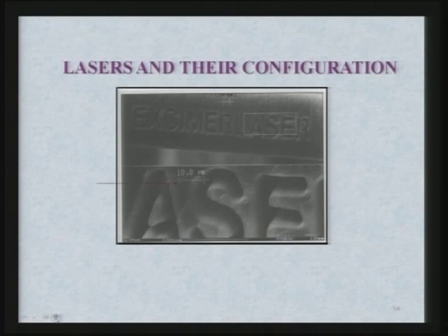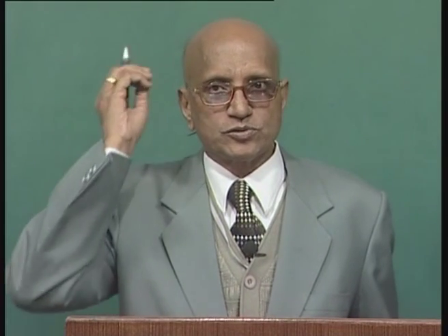Now, here is a very interesting application of laser beam micromachining, specifically excimer laser. You know, it is very difficult to write anything on hair, because if you try to write it with the help of a thermal process, it will burn immediately. You cannot apply a mechanical process for micromachining, and also you cannot apply electrochemical or chemical processes.